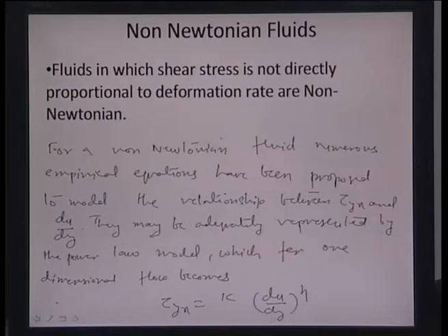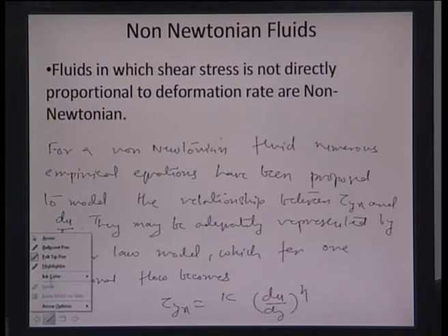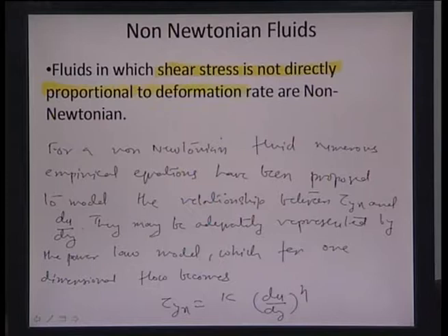In non-Newtonian fluids, contrary to what Newtonian fluids would show, the shear stress is not directly proportional to the deformation rate. For such fluids, there are numerous empirical equations which have been proposed to model them. One of them is the power law model for describing such fluids.